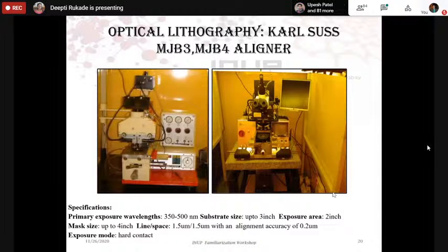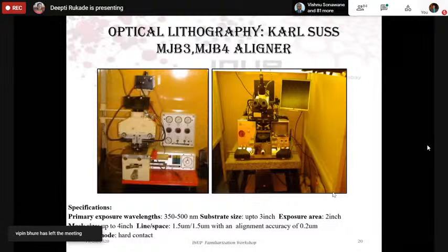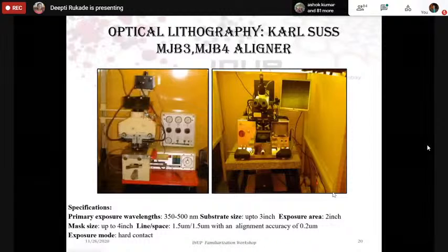If the lowest feature is 50 microns, you can get it printed from outside, because the laser writer takes up a lot of time to write those mask files. We have a few contacts, we can give you the addresses. Mostly this is done for designs like microfluidic channels, where people do not have such small features. So we get it printed on a transparency sheet, we stick it onto the plate, and we follow the same process. So this is how it goes for microfabrication.